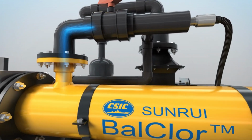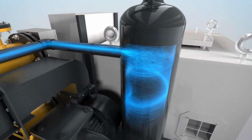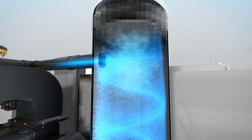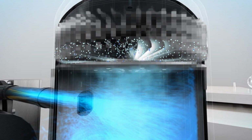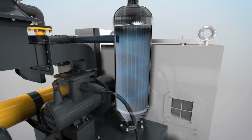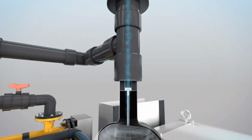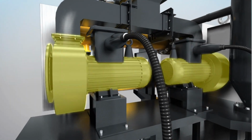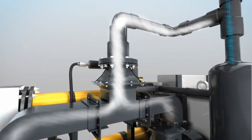Hydrogen bubbles produced during electrolysis go into a cone-type cyclone with electrolyzed seawater to generate a turbulent flow. Hydrogen bubbles are broken into smaller ones during high-speed spinning and then rise with water vapor. After a two-step separation process, vapor becomes fluid and flows back while hydrogen gas is diluted by two blowers to a safety concentration and discharged overboard through a degas pipeline.